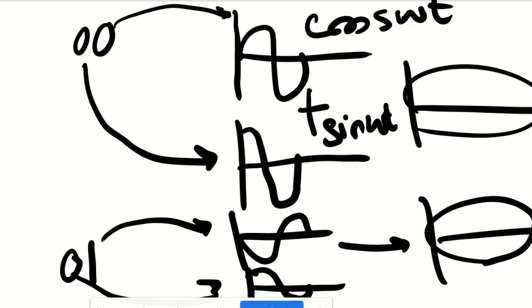That's when you have 2 bits, but you can encode more bits per phase, then you can produce higher data rate. So you can have, for example, 8 PSK, okay? For 8 PSK, that means you have how many bits? You have 3 bits sending, right? Because 2 to the power of 3 is 8, so you have 8 different combinations of data that is sent.